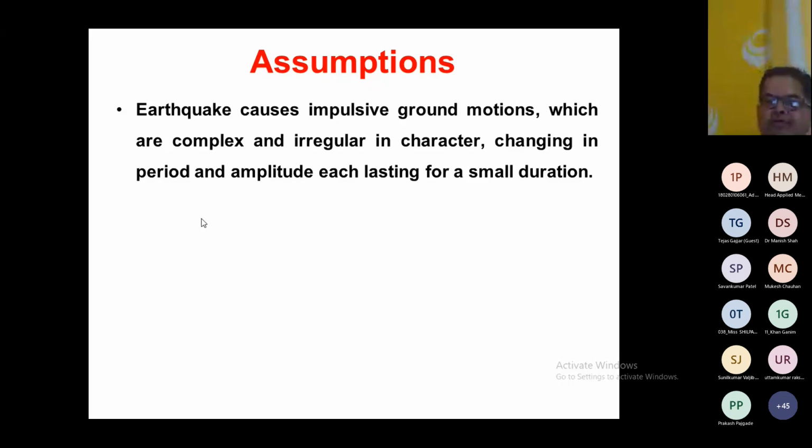So when the low frequency waves reached this filled up soil, which is soft in nature, the soft soil magnified the earthquake ground motion. The low frequency earthquake was magnified, the frequency was increased, and it matched the frequency of 8 to 15 story buildings. This is the only earthquake where engineers do not deny resonance; except for that, the code assumes that resonance is not possible.